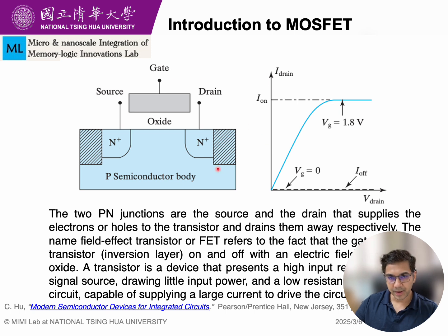Those impact the device performance and power consumption. On top of that, the choice of material, doping profile, and oxide thickness significantly influence the MOSFET's threshold voltage, subthreshold swing, and also the transconductance.